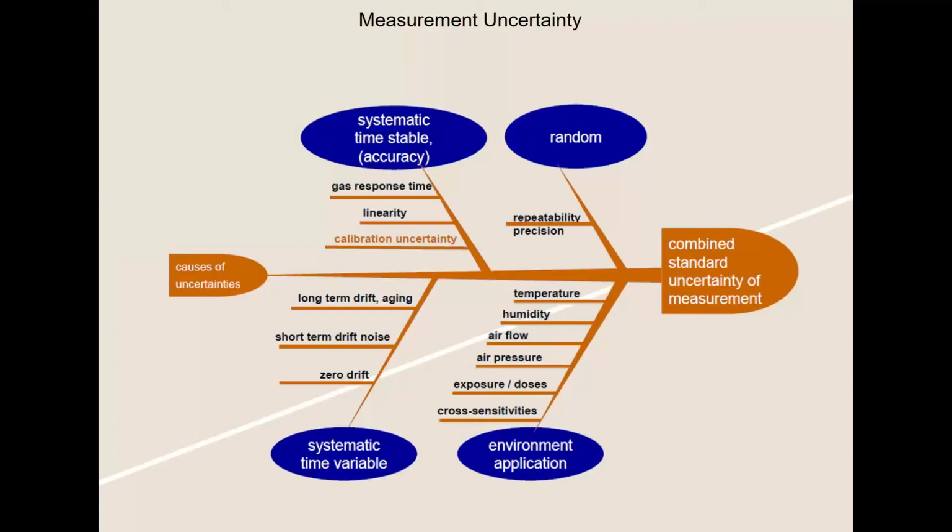So a lot of times our customers will see sensors that go negative. And a lot of times it's because of the way they've been calibrated. So if they calibrate with a very dry gas, but the ambient humidity levels are much larger, then you can see the sensor drifting negative because of the humidity. So there's different ways of mitigating that. But if we don't know that up front, then you might run into all these different issues that make it look like, oh, the sensor's not working, when it really is.